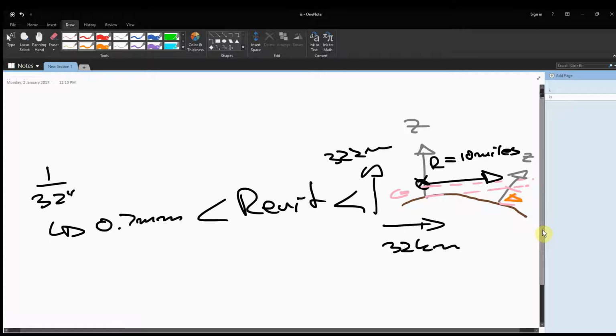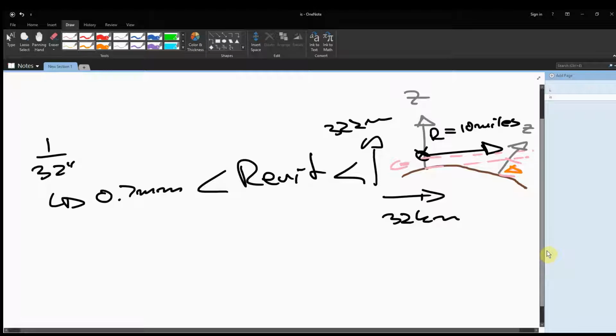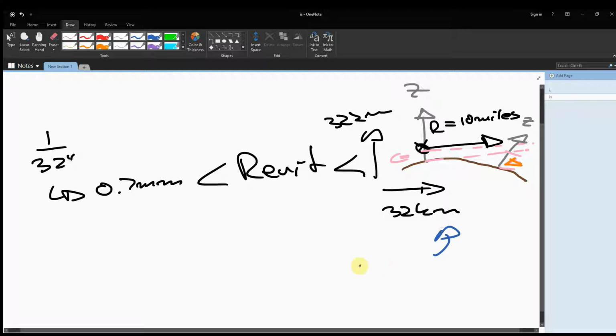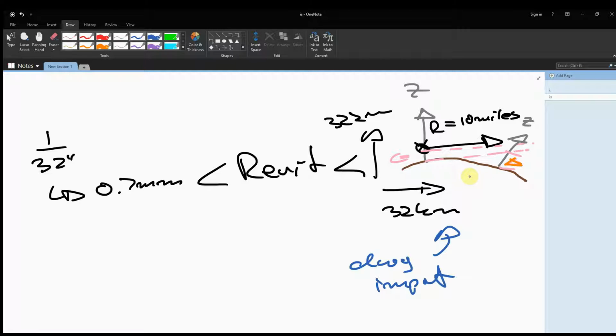When we now do an import from any DWG file, unfortunately, these limitations also apply to this DWG file, because as soon as we bring a DWG file into Revit, the whole DWG file and all the elements and objects and all the lines become parametric to each other. So, for instance, what AutoCAD or Bentley or others obviously cannot do, Revit deciphers them and just connects, because Revit is about relationships, so to say.